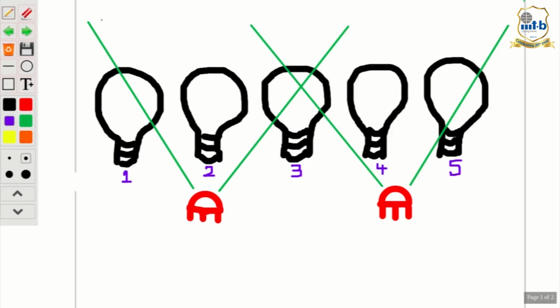As a person starts to move along this line, PIR sensor 1 will detect a high, while PIR sensor 2 will detect a 0. When this case occurs, we'll turn on lamp 1, lamp 2 and lamp 3. So if PIR sensor 1 senses 1 and PIR sensor 2 senses 0, we'll turn on lamp 1, lamp 2 and lamp 3.